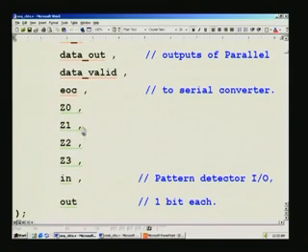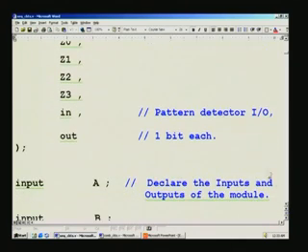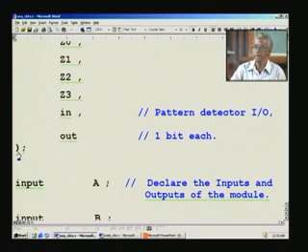And then for the state machine, to indicate every state we had put a lamp there as output Z0 to Z3, and that is also listed here, and we had finally a pattern sequence detector, and its IOs are here, both of them are 1 bit. Finally the bracket is completed with a semicolon.